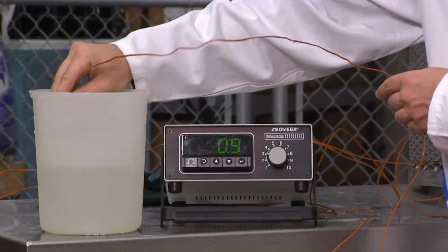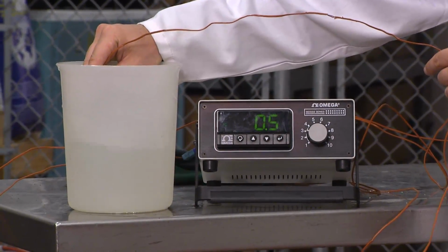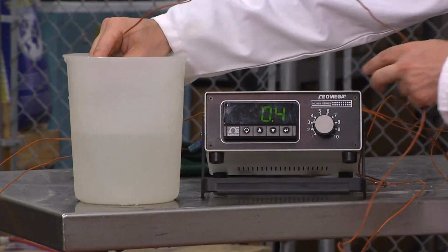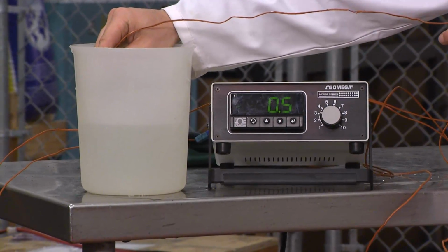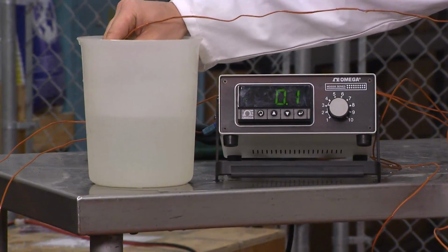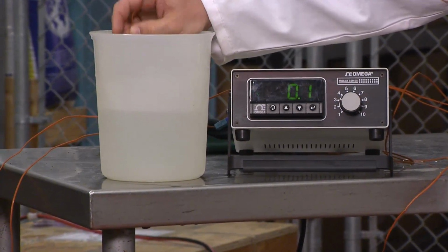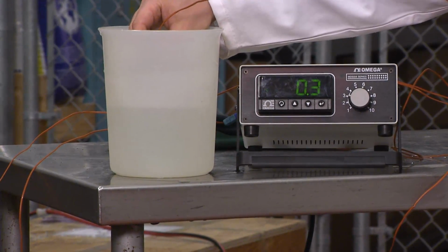We'll allow some time for the temperature of the probe to come to equilibrium with the bath. And once it has, we'll recognize that there may be an offset between the value given by the thermocouple and what we know the temperature of the bath to be. This offset must be corrected for by calibration for each one of the thermocouple probes, as they all have a slightly different offset and all require slightly different calibration.